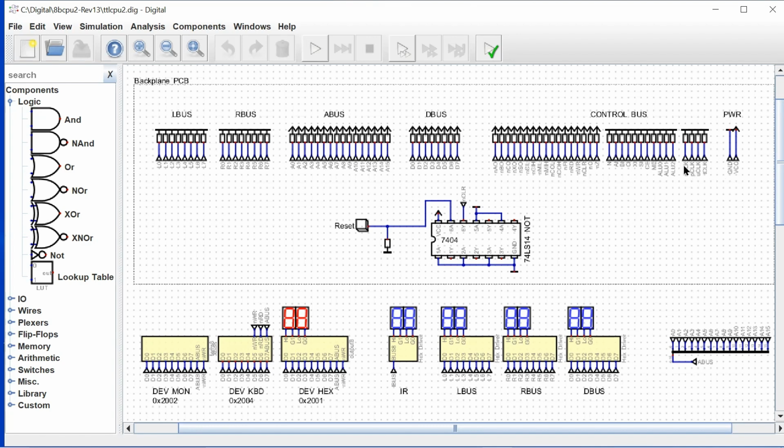to the right. And we're going to keep those a little bit separated from the rest of the signals if we can, since these are going to be the highest frequency signals. And then I also added, so we'll have one active element on the backplane. And this is just a Schmitt trigger inverter that we are going to use just to clean up and sharpen up the reset signal and do debouncing. And so that's what that's going to be for.